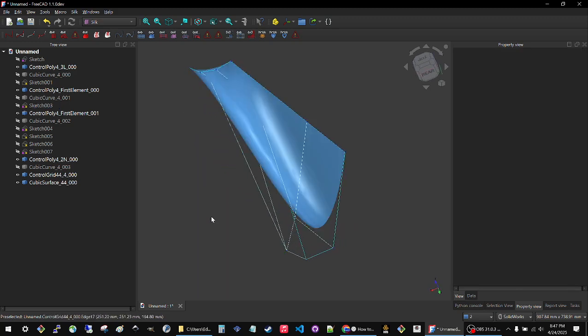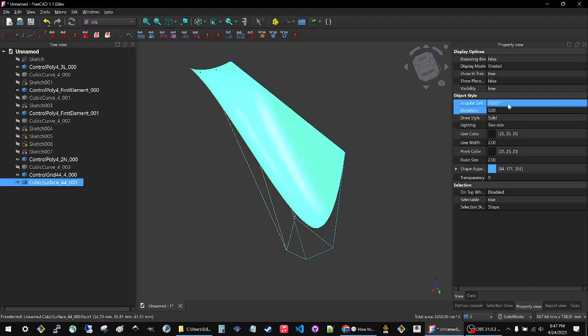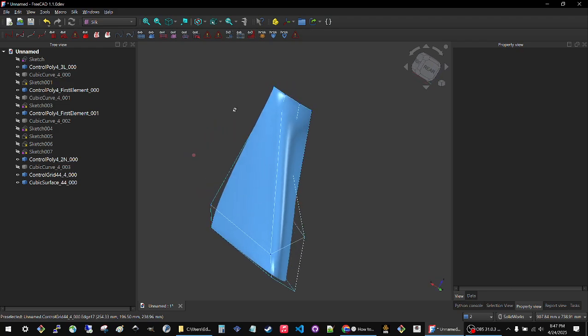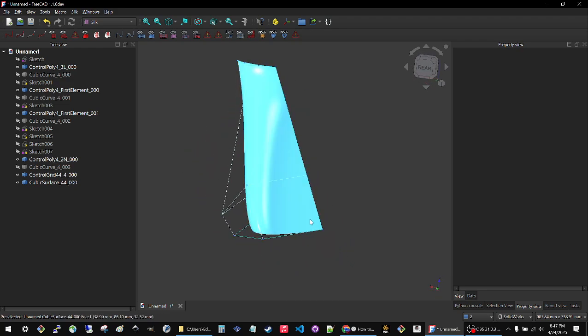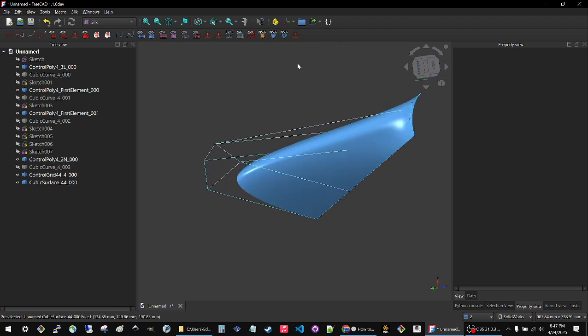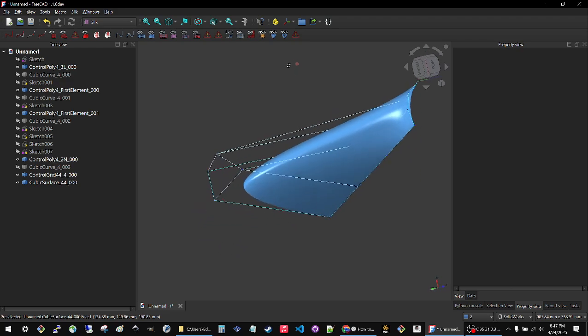So see, this is getting too ugly again. I'm going to go ahead and turn the quality back up. Let's do 1 degree. Here we go, 1 degree, and this time we'll do 0.1, so it's not too crazy. Okay. See, now that surface that looked all broken before, now it's back to nice quality. If this was part of a larger object, and the larger object looked good, there would be nothing wrong with